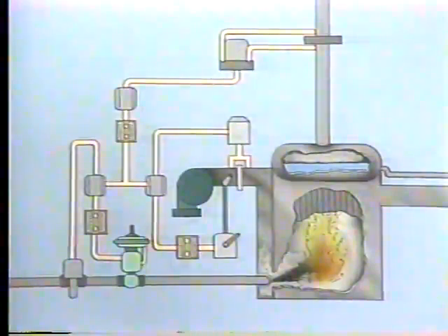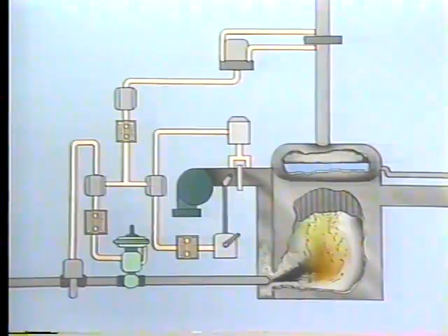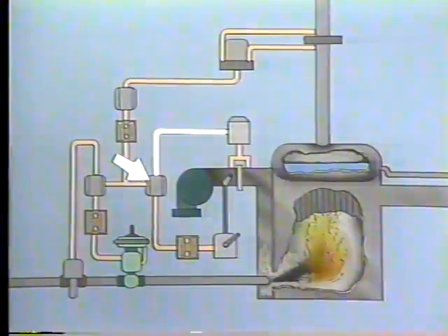The system that manipulates airflow is made up of a flow transmitter, a controller, a hand auto transfer station, and a final control element, which in this system is an actuator that operates louvers in an air duct. The master controller establishes set point for the airflow controller. This transmitter sends a signal that represents the value of the airflow to the airflow controller. The airflow controller compares the signal to the set point.